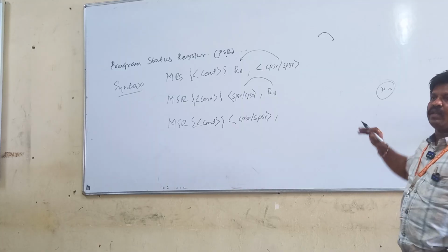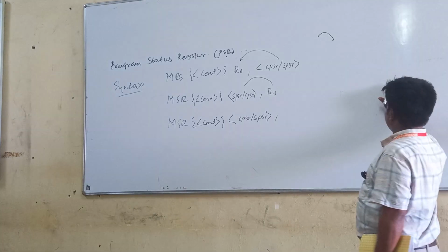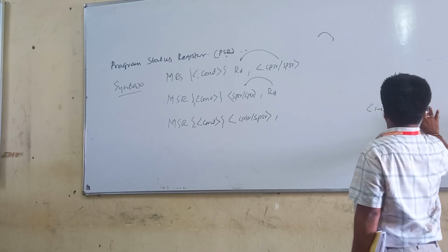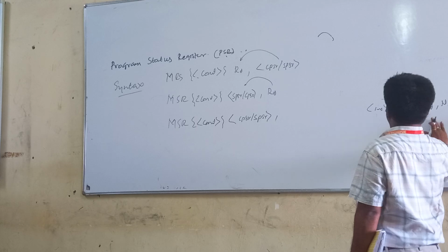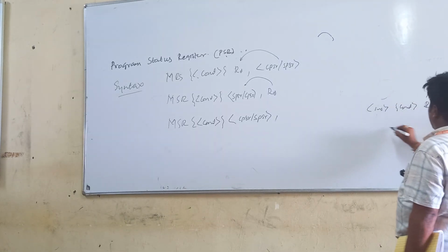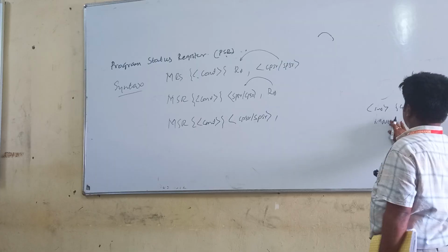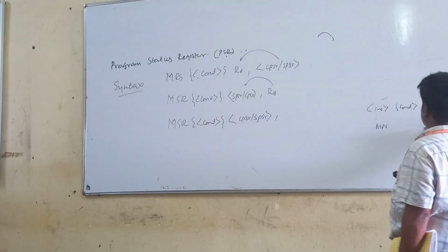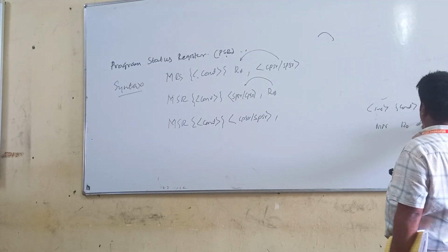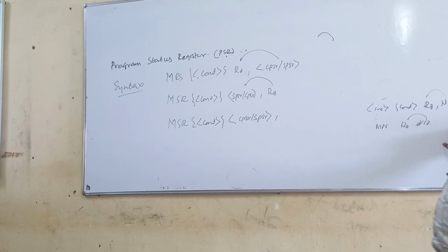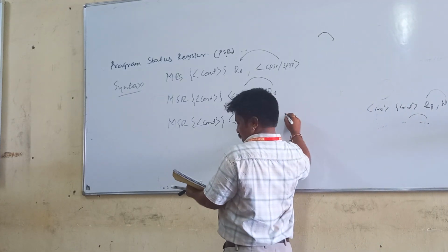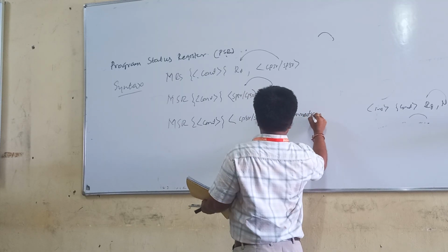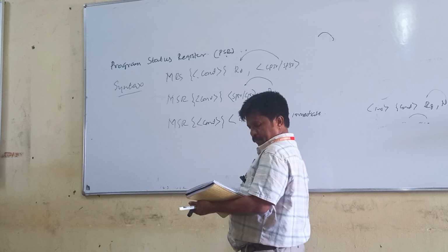We have studied this in the move instruction: the instruction, condition, then the register RD, then the n, copying the contents. In MOV, we write some condition, equal or non-equal, or there is the option of not writing it. From RD, R1, R0, we put the immediate value 10. This type will be using the immediate value here also. Okay, this is about the syntax.